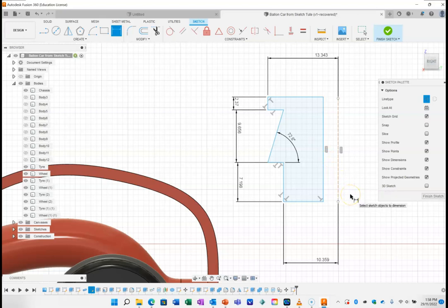The one thing I'd also need to know is that the distance of the internal hole I decided was going to be 6 millimeters. So we'll go there. That will be the distance there. So that'll be all the distances I need to set. Now I'm going to press escape. Now I'm going to start double clicking on these dimensions and setting them as I go around.